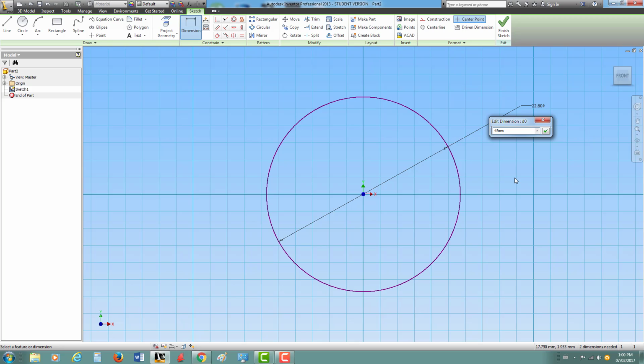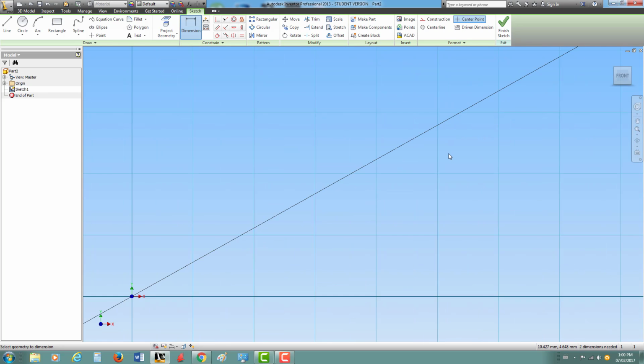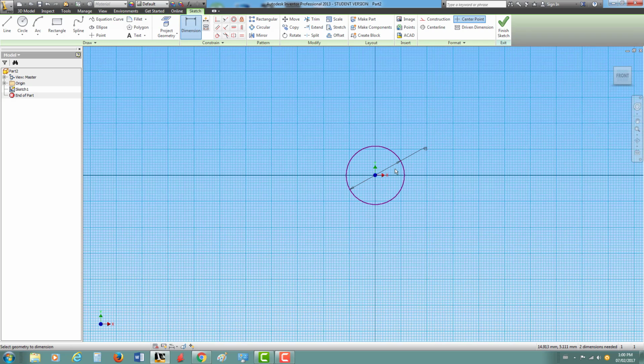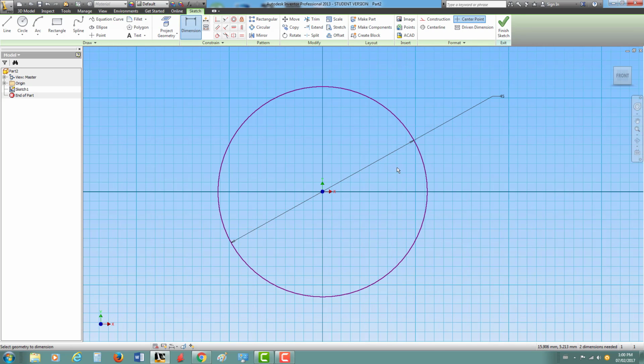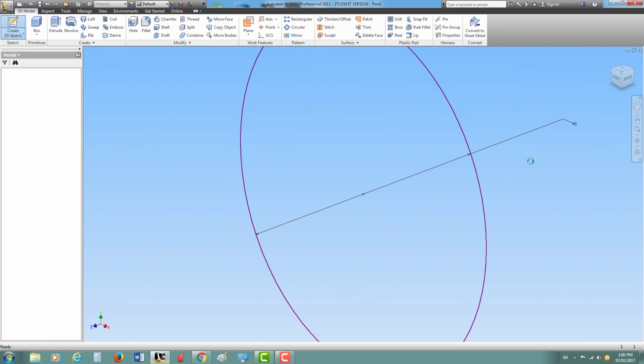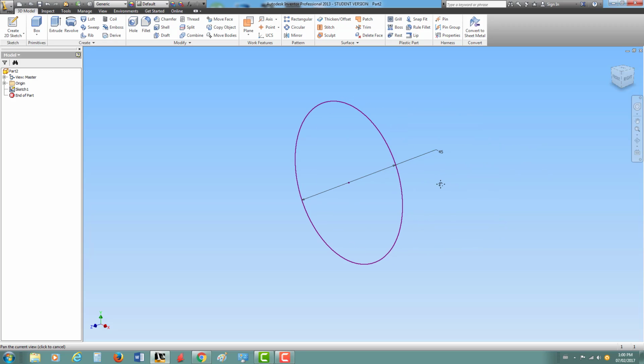So that's the constraint on everything you do. With your wheel, the diameter has to be 45 millimeters. So set that, hit enter. You'll notice now I have a slightly bigger wheel that's 45 millimeters in diameter. Now I'm going to click on Finish Sketch. And now I've got this circle.